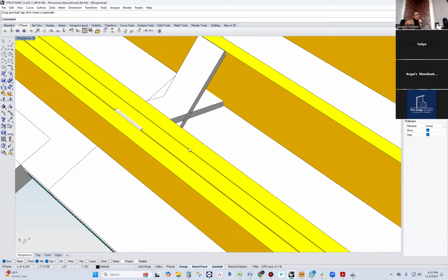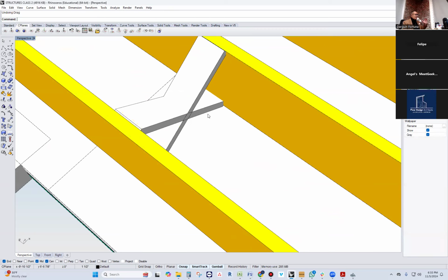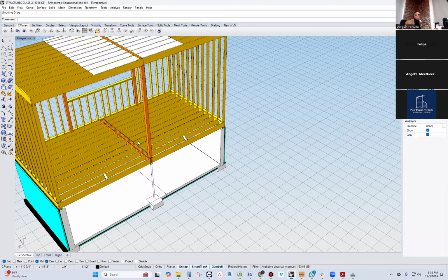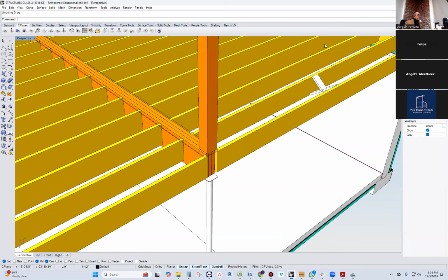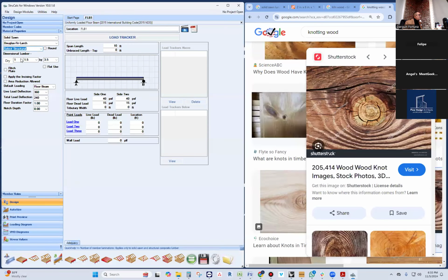If you want to call it brothering, then good, but don't put it on the drawings because people are going to laugh at you. It's not brothering, it's sistering. It's only when you do two. There's only a term for that. So this thing right here is 3 layers, and this is an LVL type of material. This right here is the amount of them that you're going to have together. For regular floor framing, you don't typically have too many together.